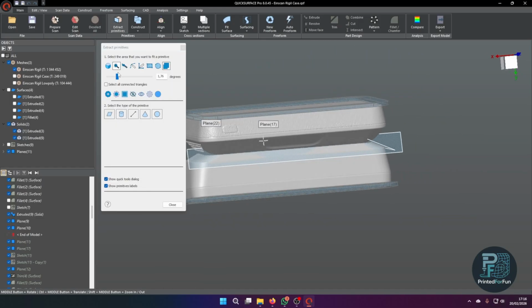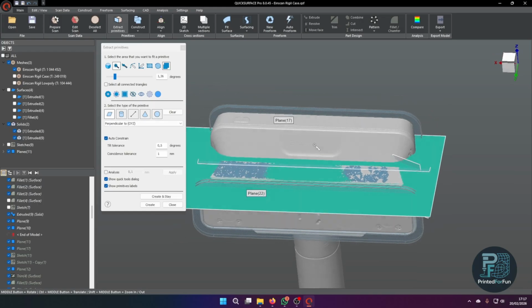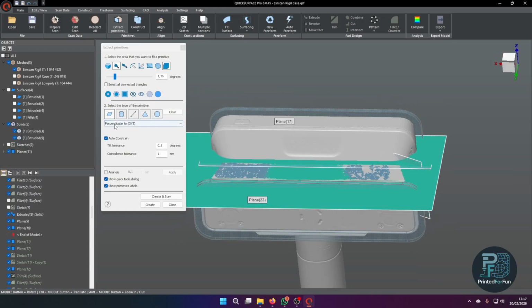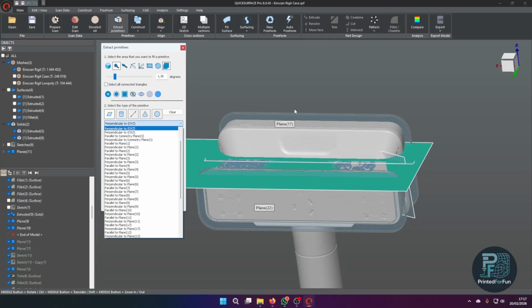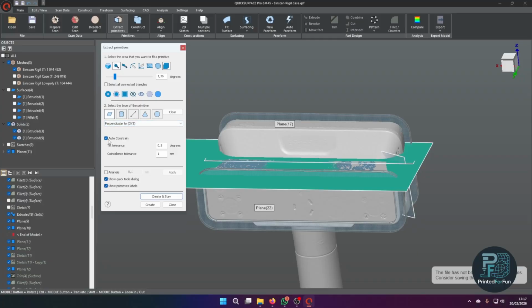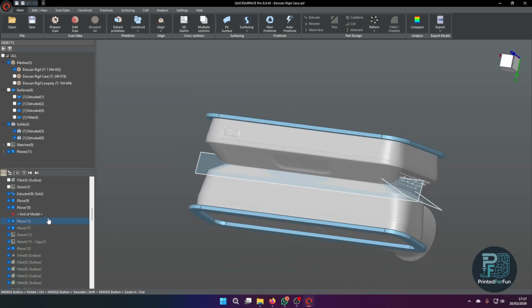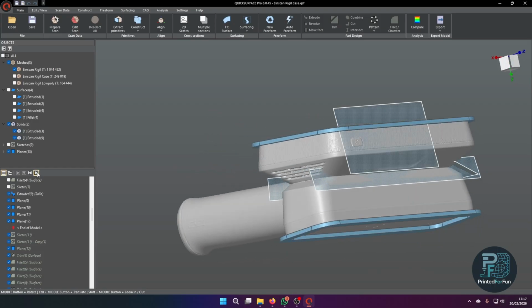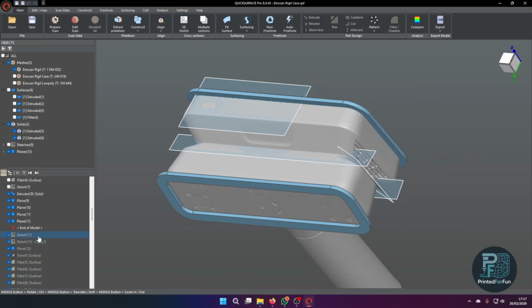Basically, it's the extract primitive function. So for example, if I now click the side like this, I can directly add a plane, and I can even constrain it to be perpendicular to the YZ plane. With the auto constraint functionality, it will do so automatically. No, I don't want to edit. So I will do this with these sides here now.